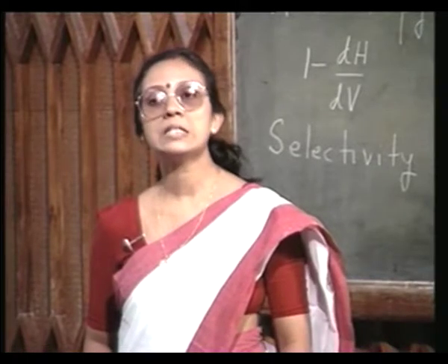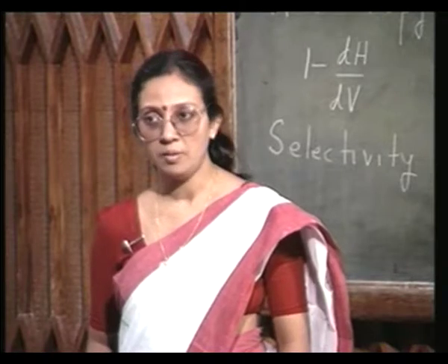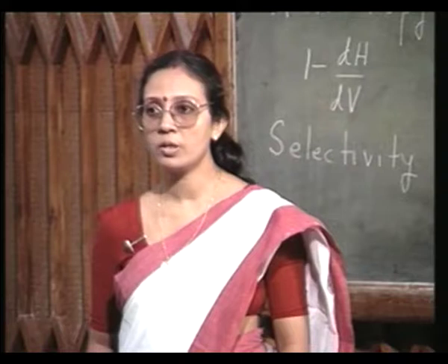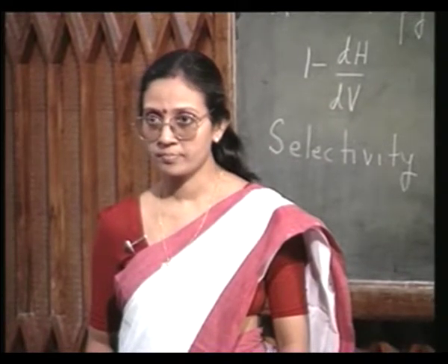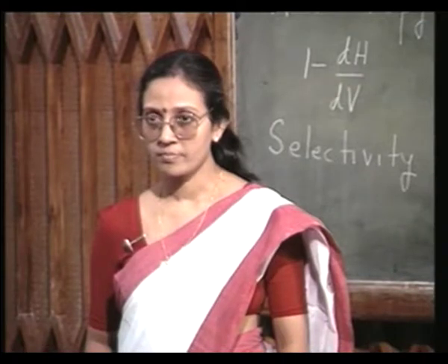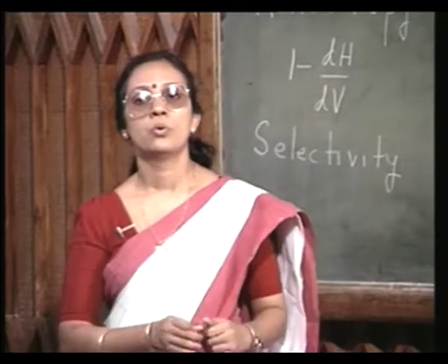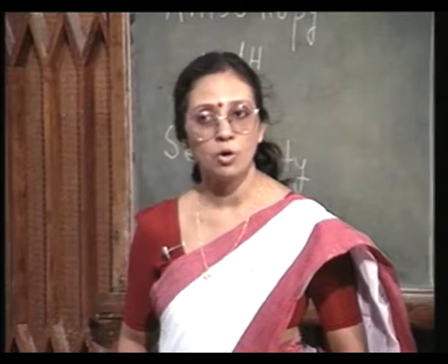Therefore, you can easily obtain good selectivity when you use chemical etching, but it is more difficult to obtain anisotropy when you are using a chemical etching system. So, with this background, let us now investigate what dry etching is all about?